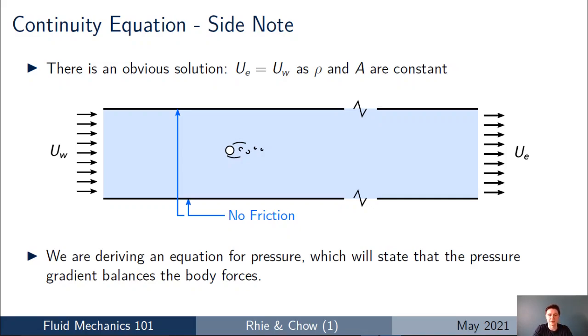And the way to understand this is if you consider a very, very long channel, which has equal area at the inlet and at the outlet, then of course this channel overall will have equal velocity. The velocity coming into the channel will equal to the velocity exiting the channel, much like our 1D cell. But of course, if we have a body in the channel or some kind of obstruction, then this body will be providing a drag force on the channel, and then of course we'll have a pressure gradient on that channel.